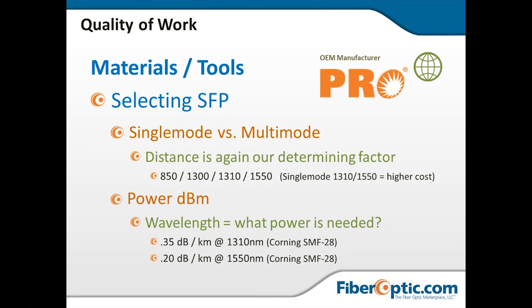which is, honestly, we would actually want a little bit of a cushion or allowance for some other factors to come in. Typically, we say have about a 3 dB kind of buffer at the end. But just kind of doing the math for you, showing you that the same length, the same fiber type, but different wavelengths and different power settings all go into the equation when you're trying to estimate what type of pricing or what type of equipment you need in your network.